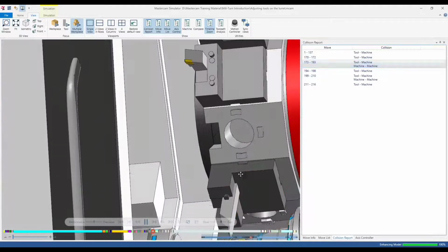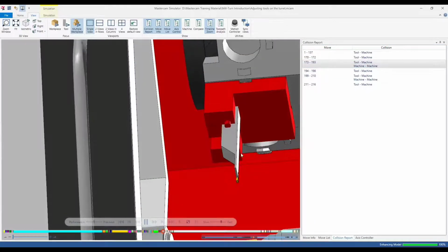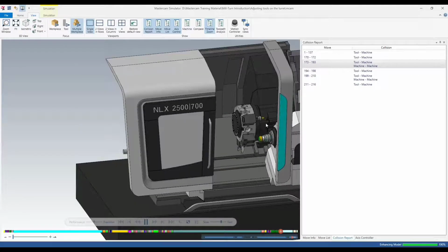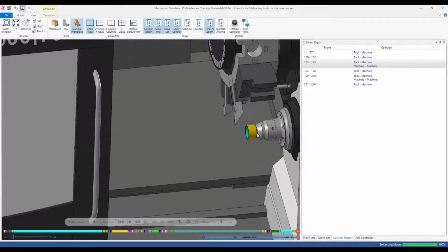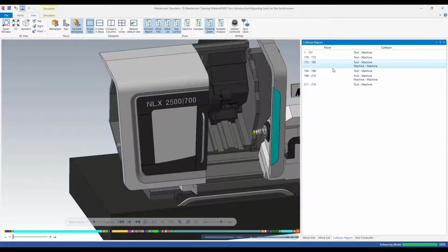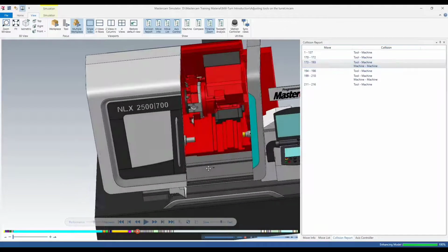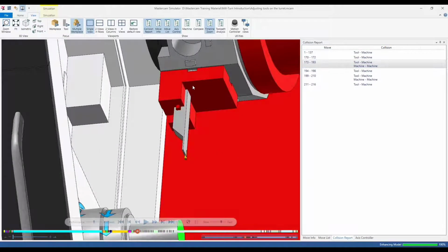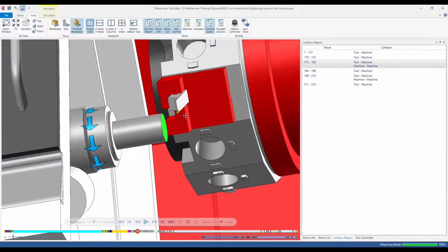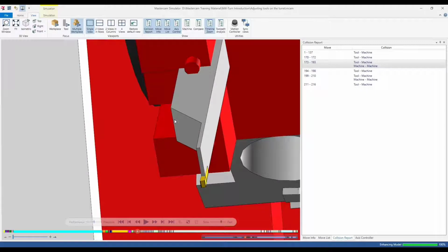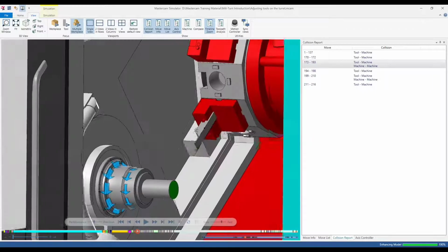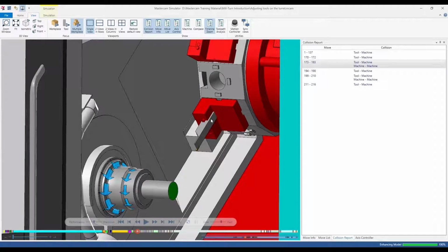And also possibly, looking at that tool, that cutoff tool can be sticking out quite a bit, so I can adjust that. Let this finish here. So let's go back here. Yeah, so I can also obviously use the correct locator for a tool with an insert down, and maybe change the stick out of the tool or the overall length of the tool.